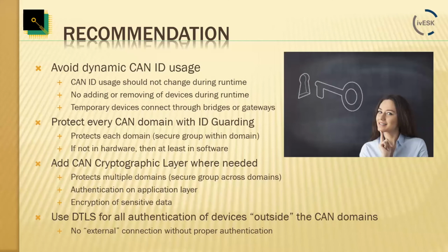Although these sorts of systems, of course, have their right to exist, and there was some reason to implement it that way, it really complicates the security aspect. So if you design a new CAN system and have to review the decision of whether we want to use dynamic CAN ID usage, and you take the security aspect into consideration, then the outcome might be different than without taking security into consideration. So that's on dynamic CAN ID usage.